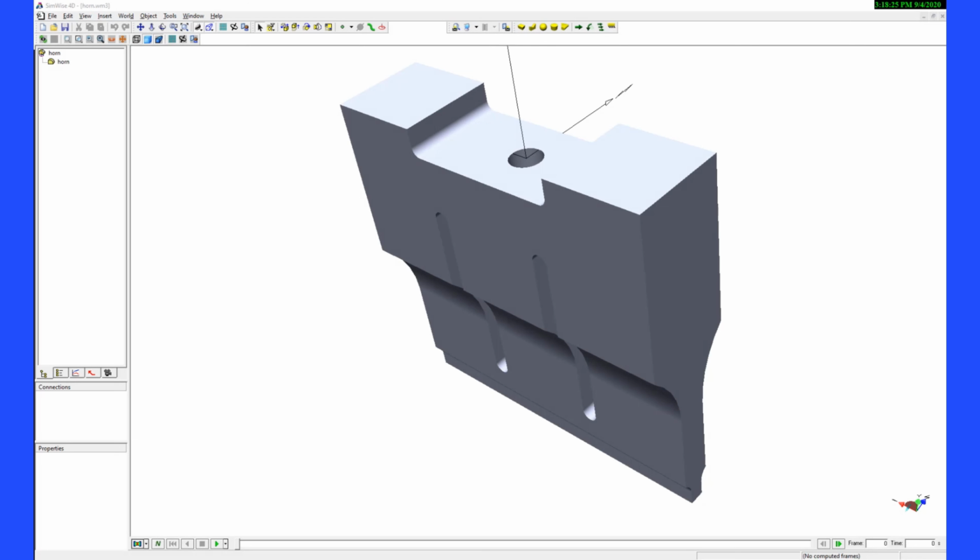This is a model of an ultrasonic welding horn, or sonotrode. It is the end part of an ultrasonic stack that transmits sound energy from an ultrasonic transducer into two parts that will be joined together at their connection via the absorption of sound energy. Ultrasonic stacks are tuned to work at certain frequencies, such as 15 kilohertz. In this example, we will look at the frequencies between 10 and 20 kilohertz and determine the maximum stresses encountered by the horn within this frequency range.